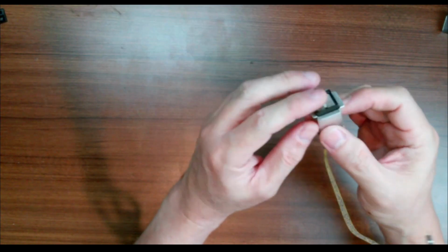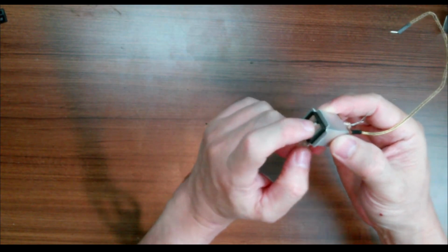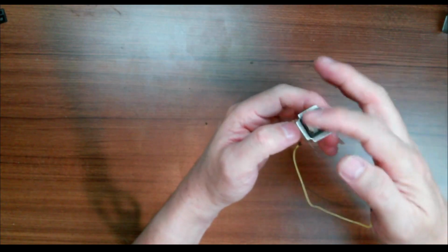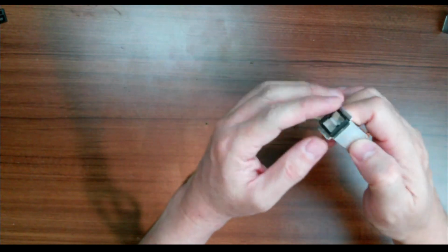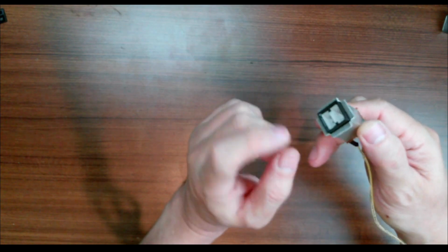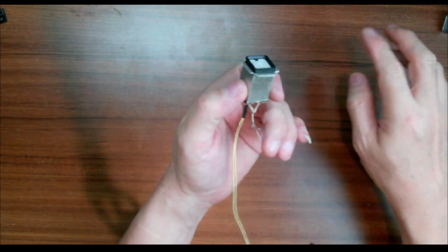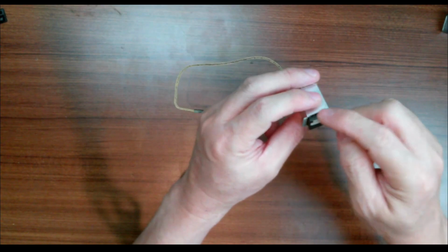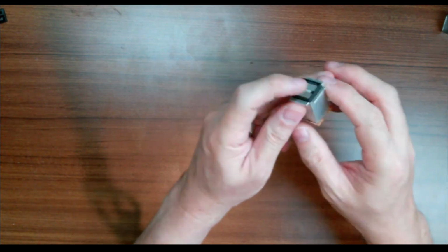By design you can do that, but when you put them together, they will have a bit of friction from each other, because you have to layer vertically like this. Well, you can do it in opposing directions to prevent some binding of the plastic, both the plastic wall and the inner side. So I prefer to use the aluminum because it ensures a smooth lining inside. I spray some silicone lubricant, and it's really reliable.